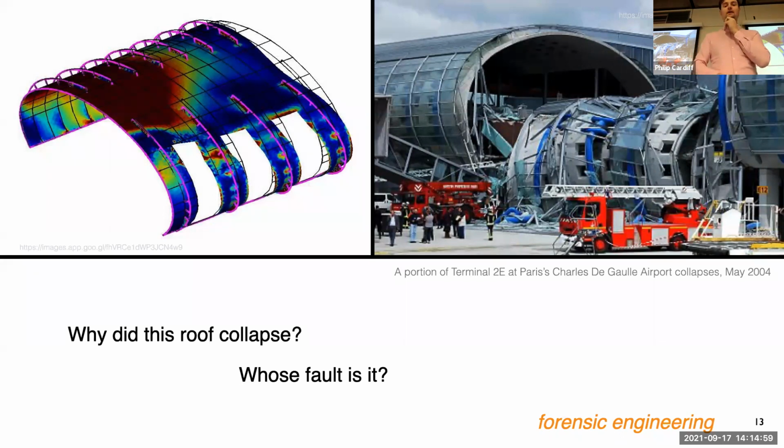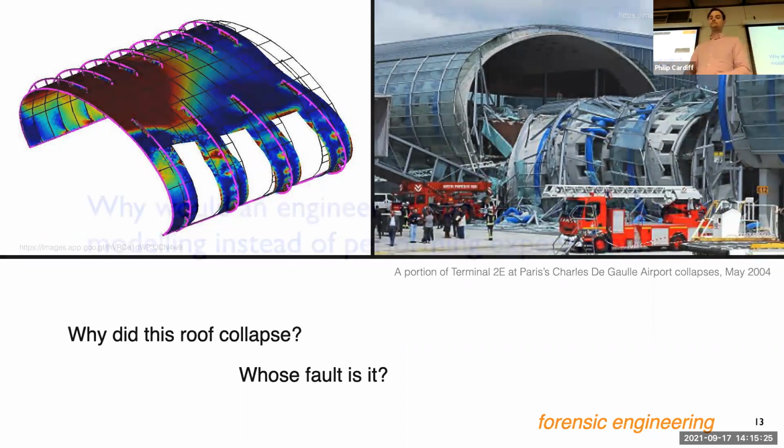And so I don't know what the outcome of that was, but I know I was involved in a separate case, like a small one in Ireland where something collapsed. I know they did stress analysis, but they basically did linear stress analysis and that ignores buckling. So if you have any thin part, if it didn't buckle, it wouldn't have failed. But thin parts fail due to buckling, not due to just overload of standard stress. So those are the kind of ways that people can mess up on things. Nobody was hurt in that case.